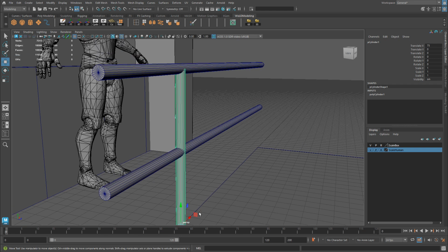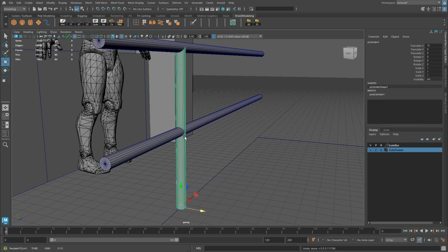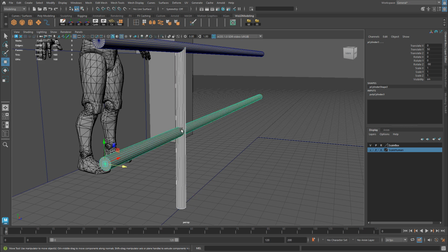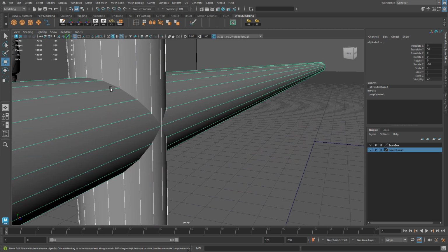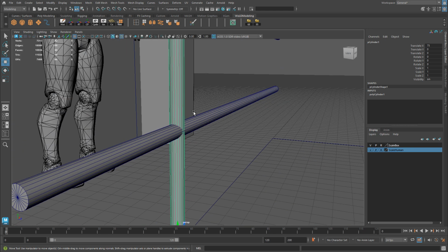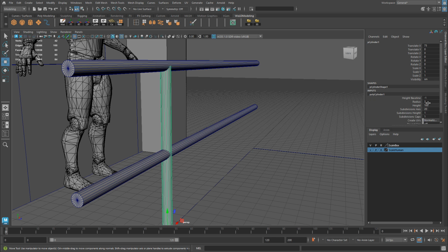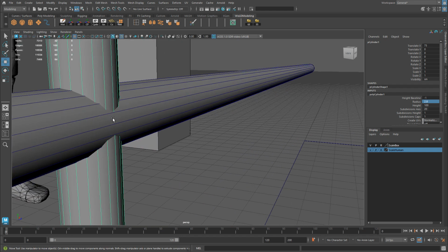So the horizontal and the vertical pieces may have some flickering due to the same size and the overlap that they have. Now, I don't want to have these pieces combined together into a seamless model where I have to model these pieces in as they would be welded together. I could, but that takes a long time and overlap is completely fine. The only thing is I want to avoid the flickering. So I will just simply take the vertical pieces and lower them in size to 2.8. Maybe 2.9, 2.7 could work, but just slightly lowering in a few units will remove the possibility of that flickering going on. You can see right here, it got smaller in size, so I'm not going to have those faces that are on top of each other flickering.